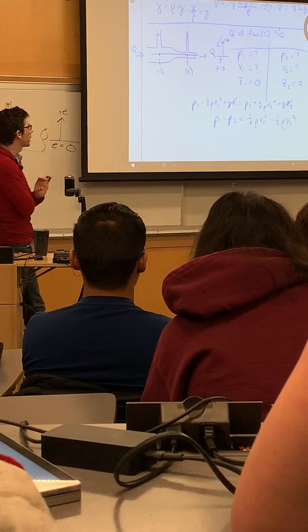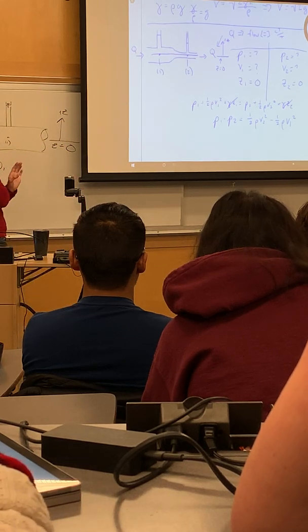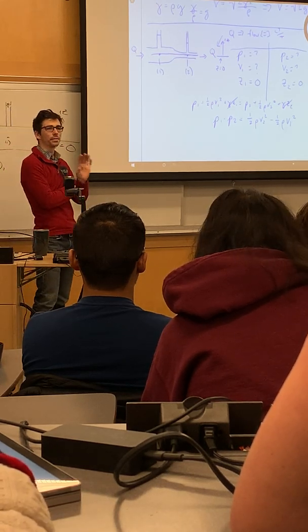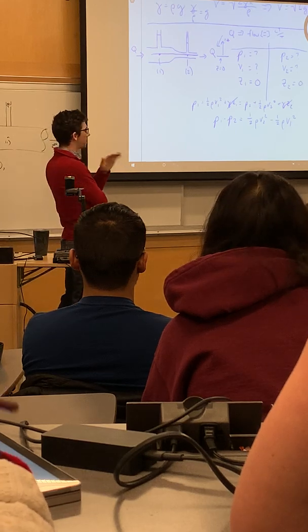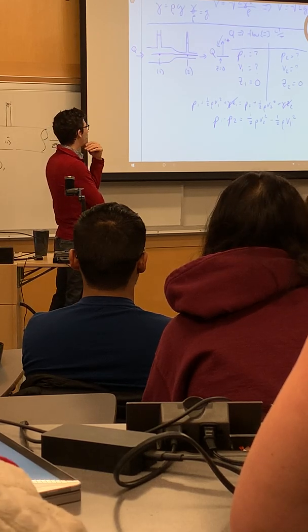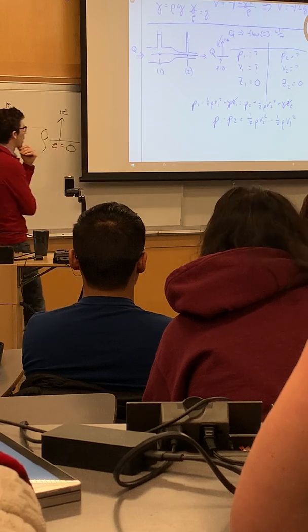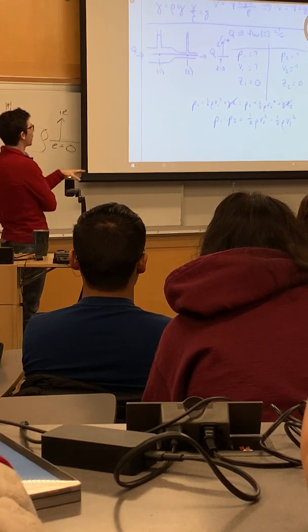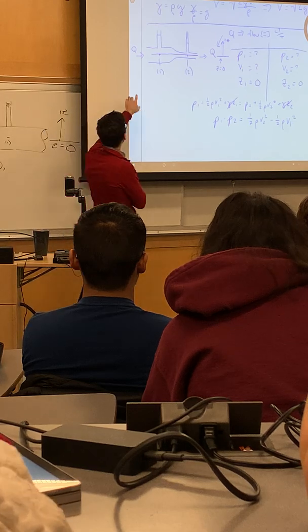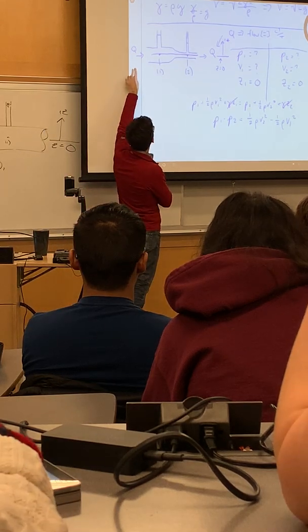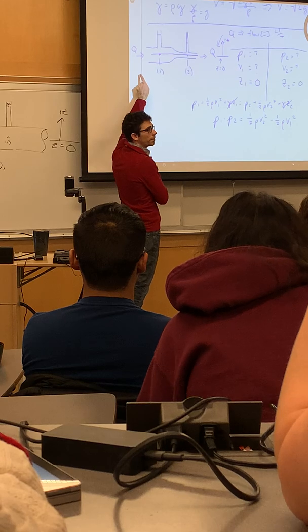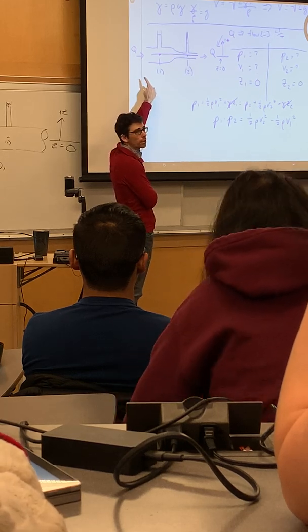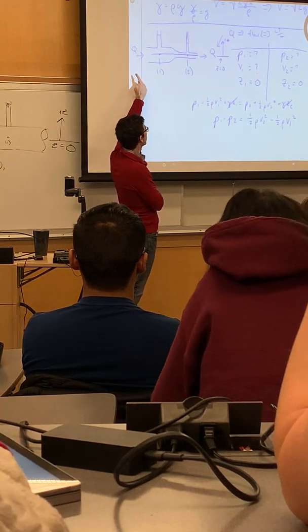And again, we're sort of jumping ahead of ourselves here. My original intent was just to talk through pressure, velocity, and elevation at each point, but this is great. This is exactly what you should be thinking about when you're applying the Bernoulli equation. So conceptually, I hope we're on the same page that Q can't change, by the very assumptions we set forth in the Bernoulli equation derivation.